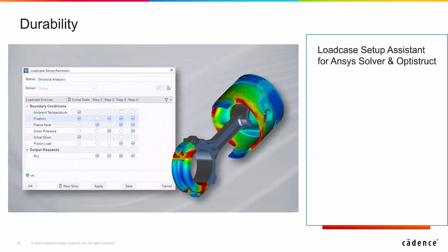The Load Case Assistant is now available for both ANSYS and OptiStruct decks. This tool provides a single, intuitive interface where users can define all supported boundary conditions, loads, simulation data, and more, all in one place. It simplifies setup and ensures consistency across different solvers.